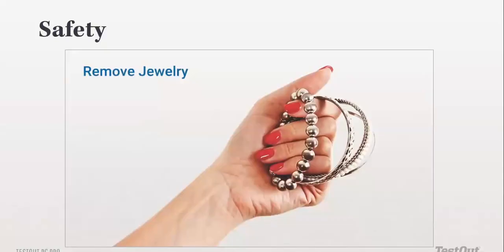Now, while you're working with electronics, some of the first things you should start by doing is removing any jewelry that is on your body. Are there wristwatches? Are there bangles? Are there earrings, nose rings, any jewelry at all that you're putting on? You have to take it off. That is to avoid electricity moving through a part that is not supposed to, to protect yourself and protect the components that you're working on as well.